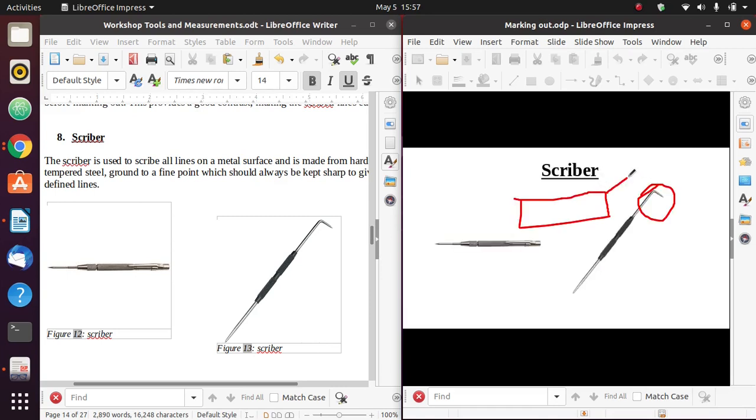It has slots and I want to scribe something inside that slot. Then this curved edge can enter and scribe those surfaces vizuri. Are we together? Yes. We use this curved edge to scribe places that the straight end cannot reach.